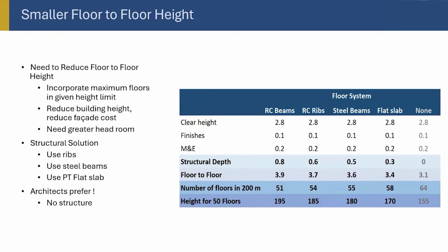And that's why many structural engineers do not understand. And they say, oh, this is very economical. It's not. For the client, it's not. That's why the total financial picture of the project should be understood. So that's why these days the bottom line is almost every tall building is now using flat slab, not even simple flat slab, post-tension flat slab, so that it's even thinner than the other one.